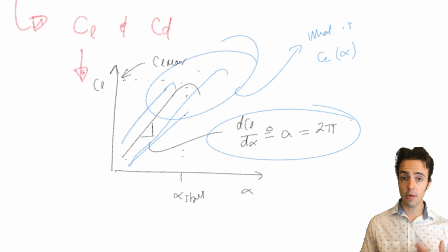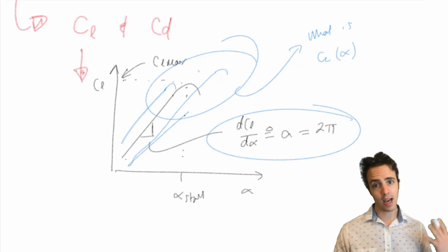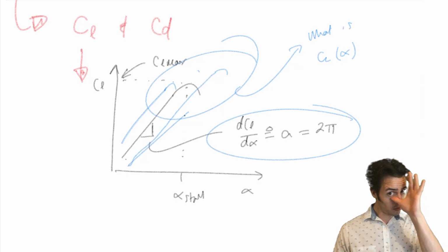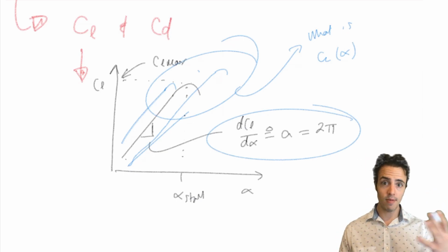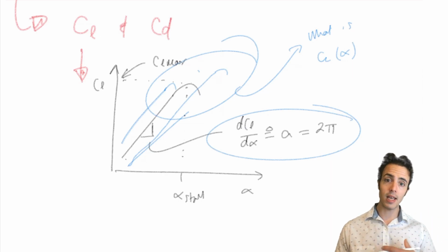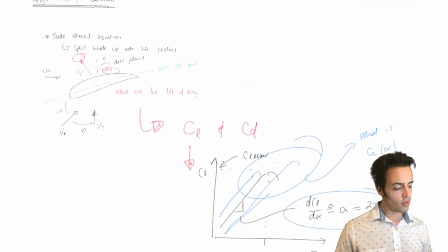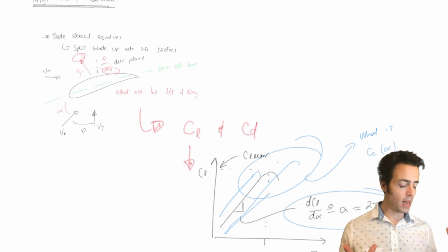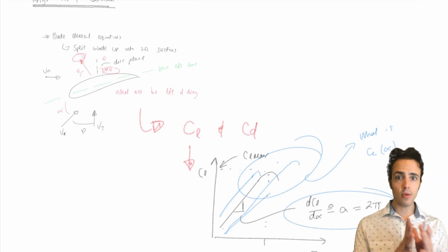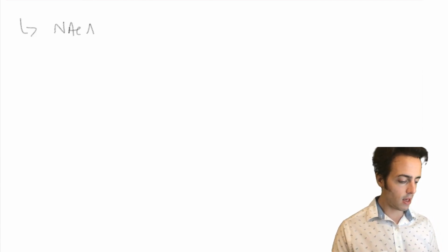We sort of know what the slope is going to be, but we want to know exactly, for a given angle of attack, what my lift coefficient is. These are also a function of Mach number for a given aerofoil, so you'll see a different variation of CL versus alpha depending on the velocity with respect to the speed of sound. So we need to know CL and CD versus alpha for the sections of a propeller. We're going to determine where we can get them from. What we're going to initially look at are NACA 16 sections.